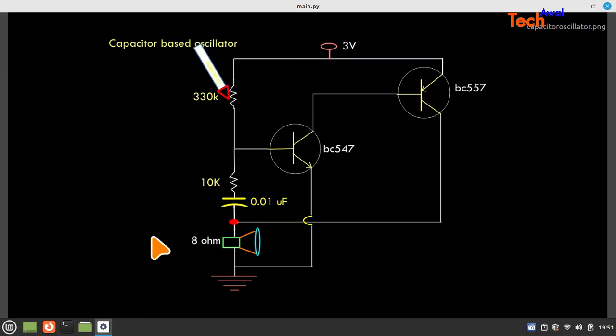Okay, now if I connect this circuit, if I think that there is a switch and I connect this circuit, so as per the characteristics of a capacitor, a charge would start accumulating in the capacitor. Okay, so at the beginning when the capacitor is discharged, this would behave as a short circuit.